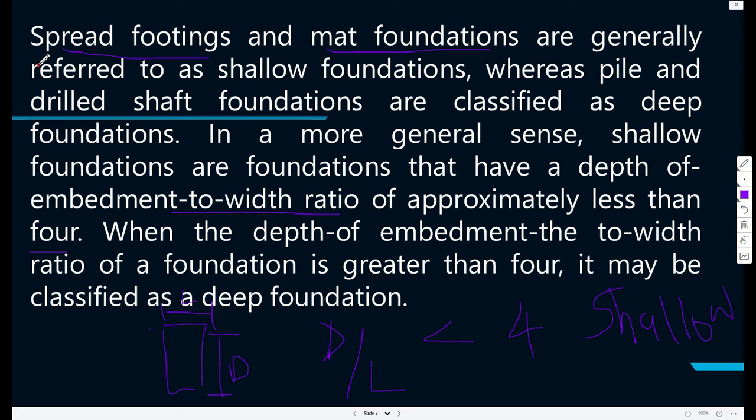If you want to know a distinction, then you check the ratio of the depth to the length. If it is greater than 4, then we are talking about deep foundations. If it is less than 4, then we are talking about shallow foundations.